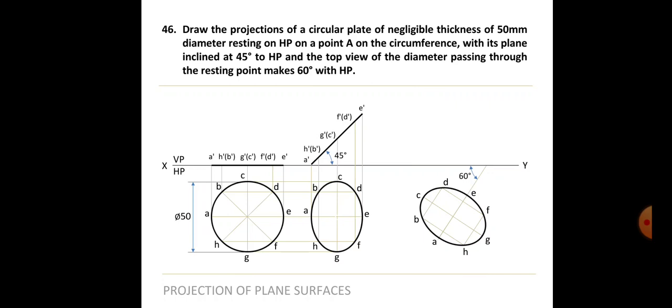Okay. So now that we have got all the points A, B, C, D, E, F, G, H, we have to get the final front view. And how do we get that? We project all the points from the top view upwards, like this, and also draw the projections from the front view in the second view. That is the line A dash, B dash, C dash, D dash, E dash projected. So you will project it, and also as you can see how I have projected it.